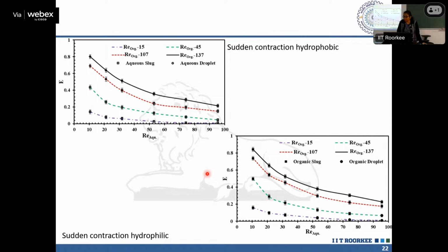Yes, absolutely. So in the second case, it is the hydrophilic one. So water is the continuous medium, and we have slugs of toluene having much lower viscosity than the continuous medium. Always the viscosity is around half. Okay, so the circulation, which we have observed through our simulation, I have shown you, if you recall, in my second lecture. The circulation inside a low viscosity slug is always higher, and that is the reason why we are getting higher efficiency in this case.